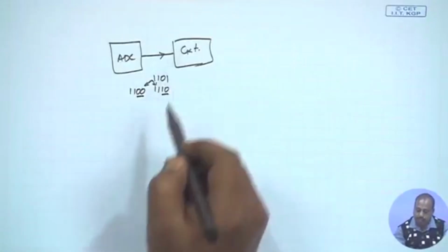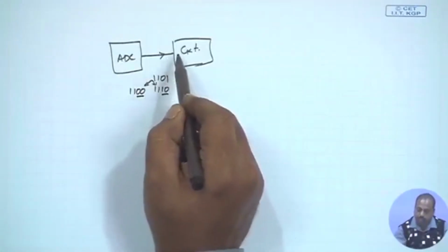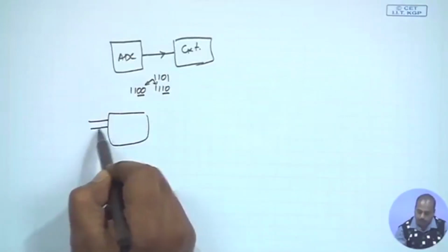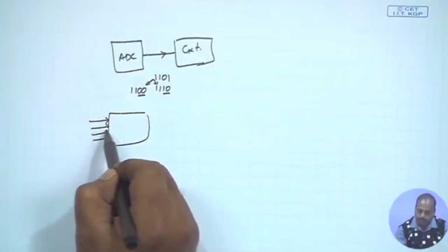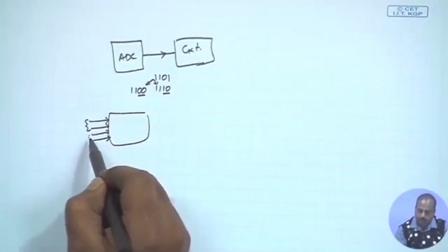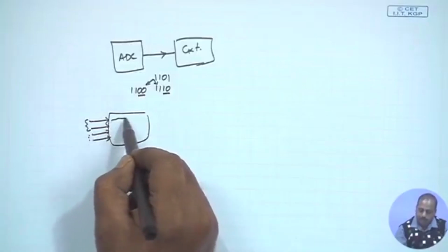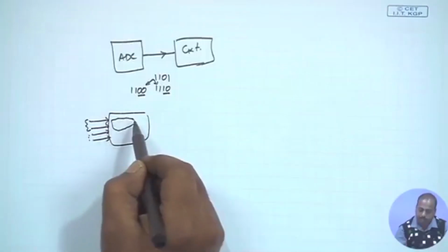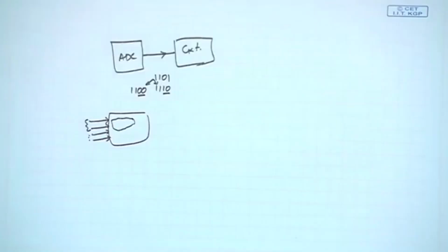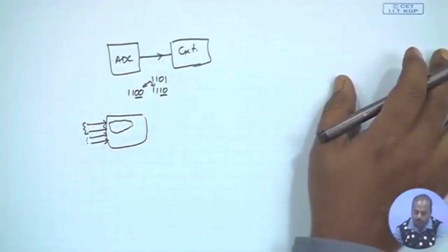Now this is a circuit where these 4 bits are coming as input. So in this circuit I have got these 4 bits coming from the ADC given as input, and if these 2 bits do not change their values, only these 2 bits change, then a large part of the gates that we have in this circuit will not switch. And we know that in CMOS technology, the power is consumed only when this switching occurs. So in fact this is due to this dynamic power.